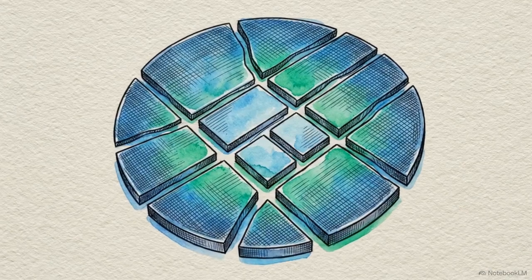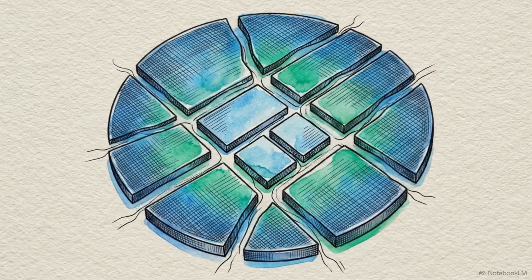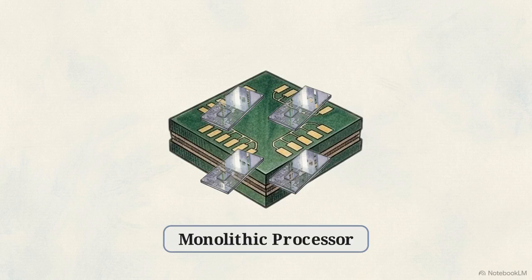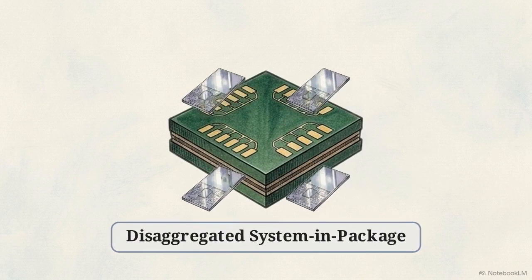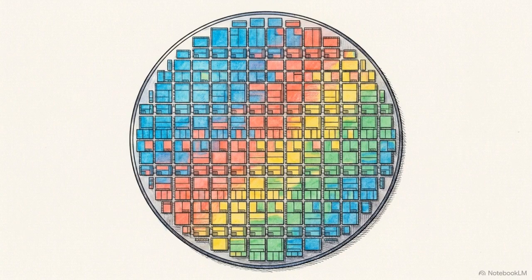As processing demands escalate, single monolithic silicon chips are hitting the reticle limit, the maximum physical size a fabrication tool can reliably print. To bypass this physical constraint, manufacturers are disaggregating large chips into smaller, distinct modules. Printing smaller dies directly increases the number of usable chips per wafer, optimizing the overall manufacturing yield.